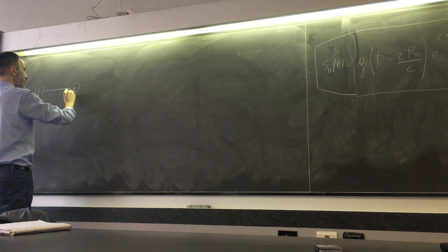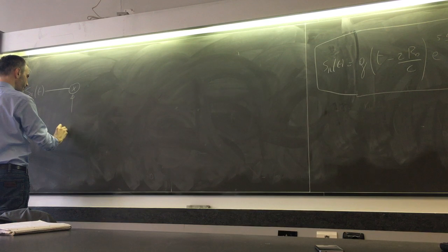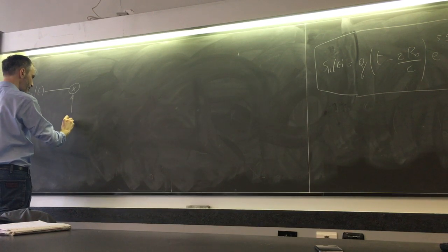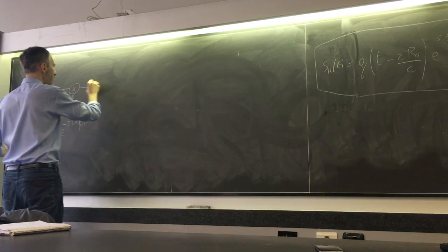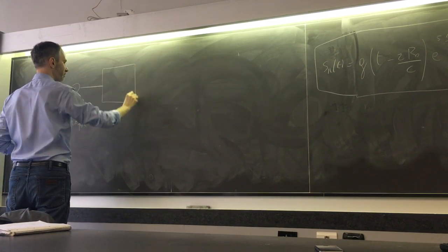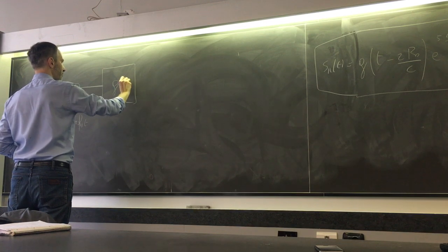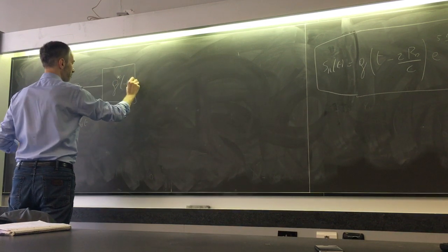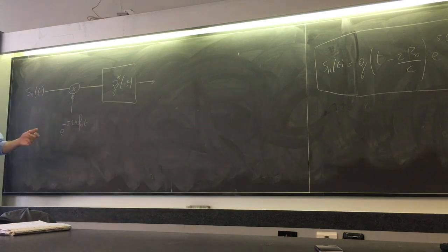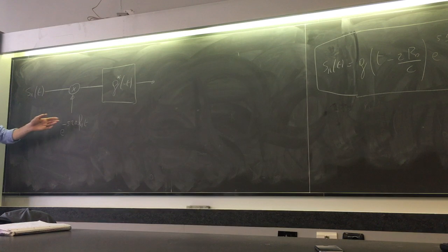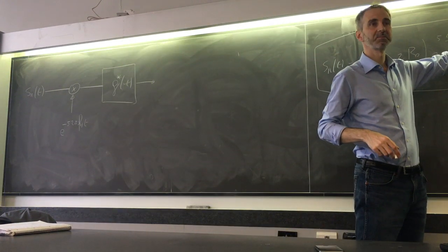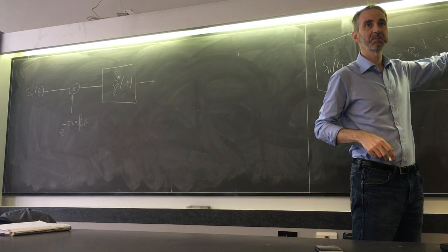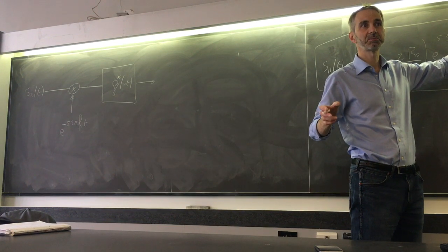You counter-rotate the signal by the Doppler frequency, and then you apply your matched filter. You are just cancelling this term out this way. So everything is perfectly recovered.